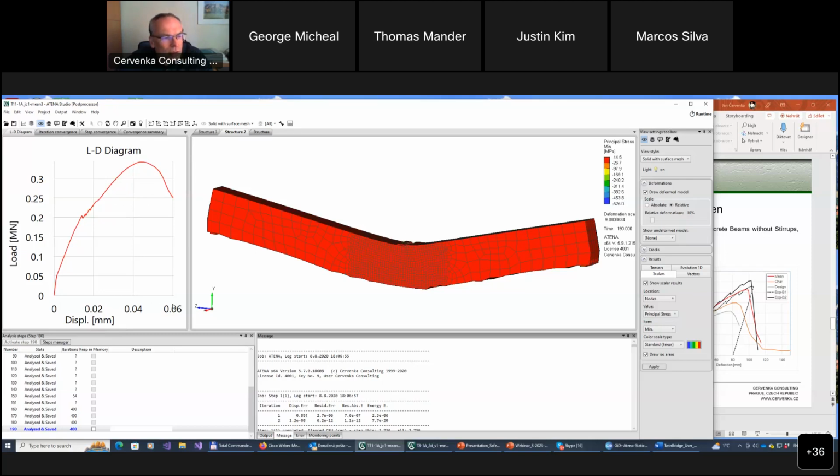In this case, I have one monitor measuring the maximum deflection. This is shown on the horizontal axis. And then I have a monitor which monitors the applied load here in the middle. Coming back to the first question, because it is a simulation of an experiment, and the experiment is loaded by a single force, it is better to control the analysis by prescribing displacement. If we are prescribing displacement, then we should put a monitor monitoring reaction, because as a result, the force is actually in the reactions. And this is plotted on the horizontal axis.